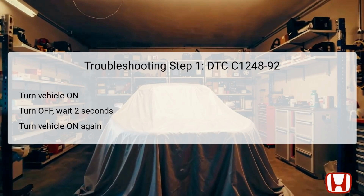The first troubleshooting step in addressing DTC C1248-92 involves performing a basic confirmation procedure to gauge the condition of the system. Begin by turning the vehicle to the on mode without starting the engine. This initializes the vehicle's electronic systems.